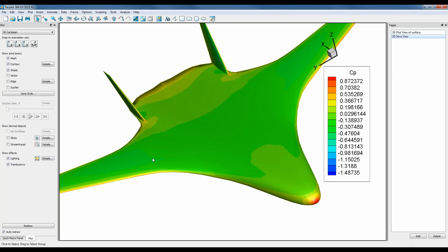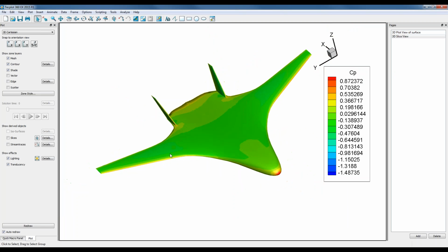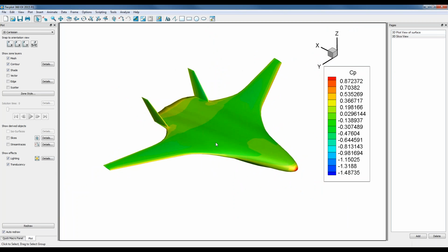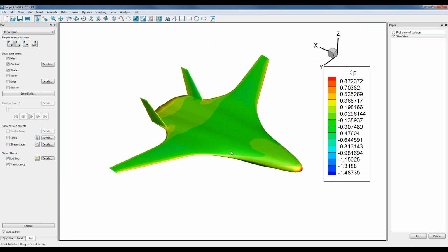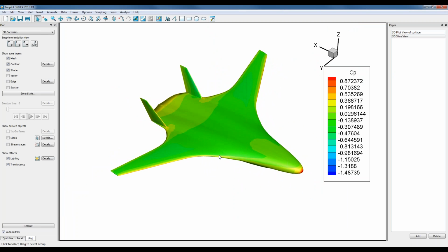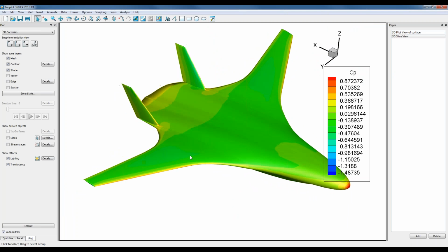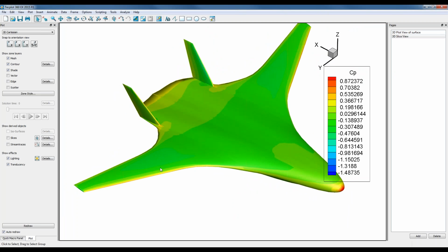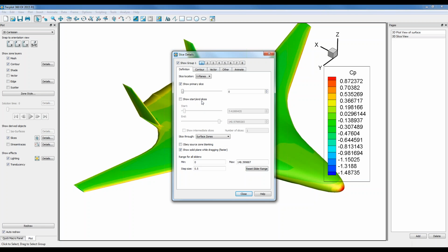And now let's go ahead, and I want to talk about a couple of things, and this is data extraction. This first part of the tutorial is primarily just to familiarize those people who are not using 360EX today, maybe don't know some of these capabilities exist. So we'll start with some new enhancements to the slicing. We're going to look at a Y slice, and you can see that there are three types of slices we do now: you can select the surface of volumes, or you can just do the volume zones.